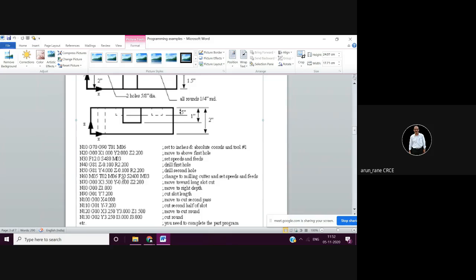See, technically nothing is wrong. The tool is changed and you can start the spindle, but it is not good actually. It is always good practice that you bring the tool here above the surface and start the spindle there. That means you stand the drill here and start it here. Right now what is happening is the reference point is here, and from here you start the tool and bring it over here. Technically nothing is wrong, machining time wise nothing is wrong, absolutely no problem.